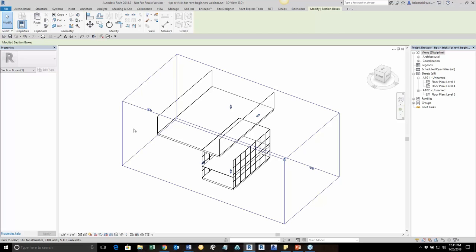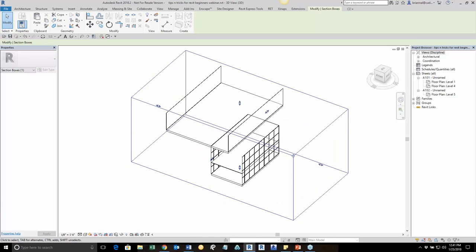Related to family editing, creating a family component rather than a model in place is always recommended. Using model in place is really only recommended for those one-off, very custom situations. So in the example that it's a very customized front desk or something like that, then we advise to build a model in place. Otherwise, building an actual family would be our recommendation.